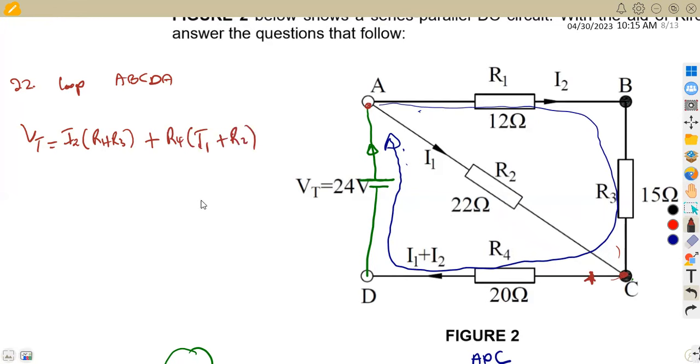All right, so that is what we are going to have. This is I1 plus I2, not R2. This is I1 plus I2, current times resistance, times the resistor R4. So you work with the branch from C to A. This is the same branch which has got I1 and I2 as the current that is flowing in that branch, but there is only one resistor there.